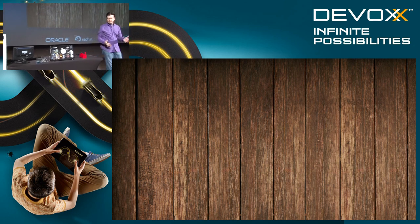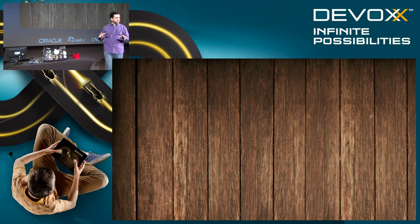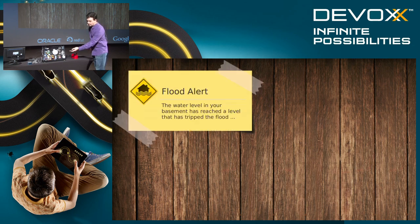So we wanted to be aware if we had a flood condition. If water were to rise in our sump pump area in the basement, this little float's going to lift up, and there's a magnetic reed in there that, when we lift the float, which contains the magnet, is going to trip the sensor inside it and complete our circuit, therefore signaling high our GPIO pin. So when I raise this, we should get an alert. There, so we've got our flood alert, which on screen, you can see it up here.